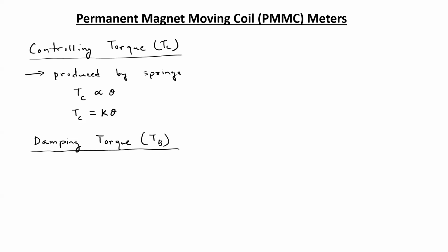So this eddy current that is producing a magnetic field which opposes the main field, which eventually slows down the swing of the pointer, is actually introducing some sort of damping to the system. So this prevents the pointer from rotating at high speed whenever it experiences some deflecting torque.